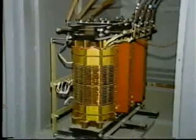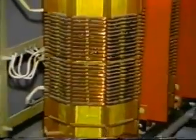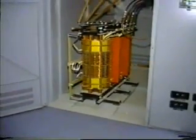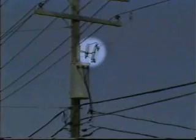As with substation transformers, not all distribution transformers are oil-filled. In some applications, dry-type units are used. These transformers are housed in a metal enclosure and cooled by natural circulation of air. Even though the coils are widely spaced, these units still run quite hot. Conventional pole-type transformers do not normally have any protective equipment built in. Instead, it is up to the utility to provide external surge arresters and fusing for protection.